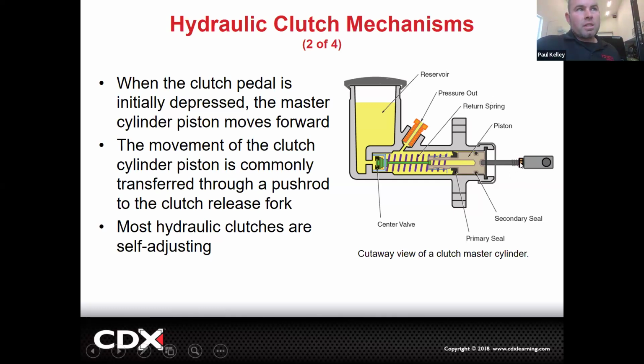You back up right here, this is that push rod. So if we were to loosen this lock nut and turn this push rod longer, and they were to bottom the pedal out, now you can see how this push rod will start to push on this piston. And if it starts to push on this piston, it'll build pressure. And that'll actually start to release your clutch and cause a slip. So that's the same push rod.